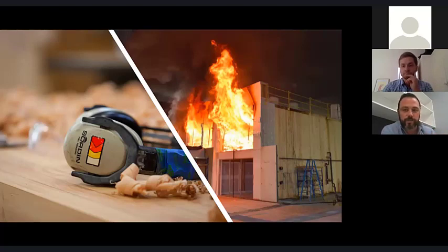The first few jobs are fully encapsulated because it's easier to get it approved. And then we start peeling it back and looking for really efficient ways of exposing it. But my advice is to really engage with suppliers, acoustic consultants and fire consultants, so you're not caught up in exposing that wall, and then they say, look, guys, I'm sorry, but that's going to cost you a lot of money to expose that wall. How about this wall over here? Try to work that into the design early.